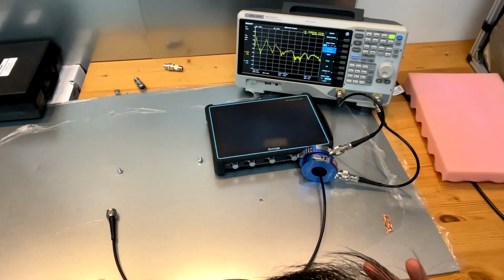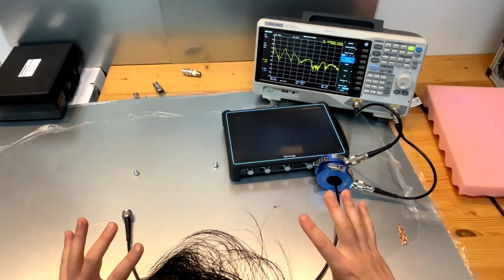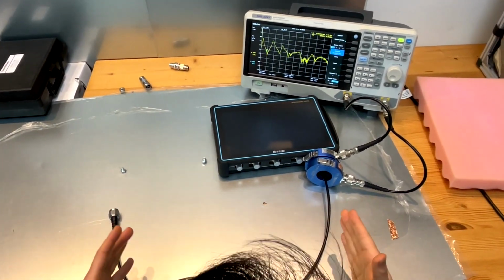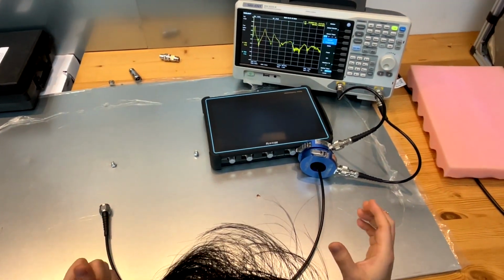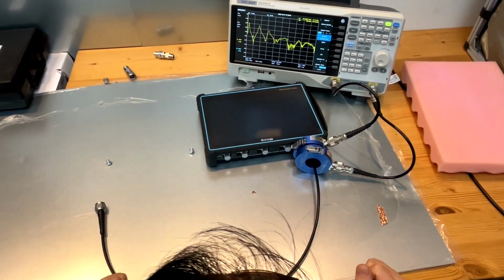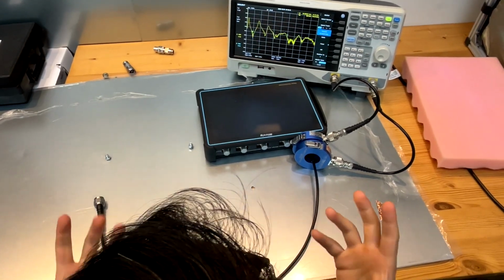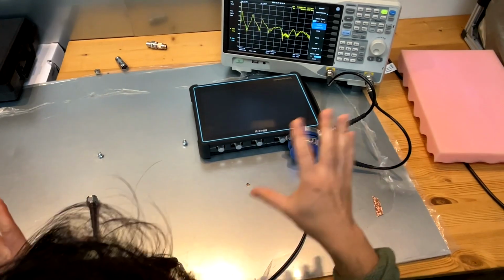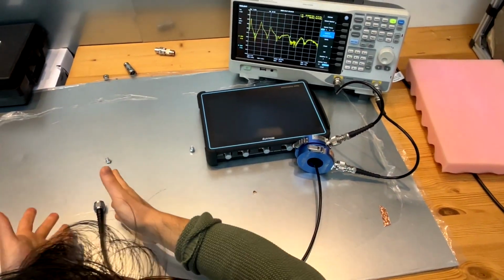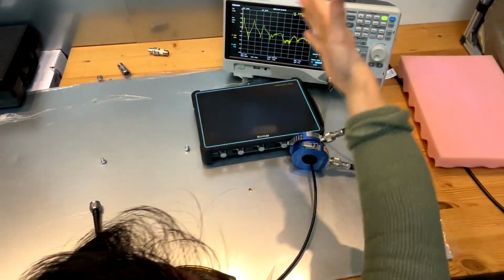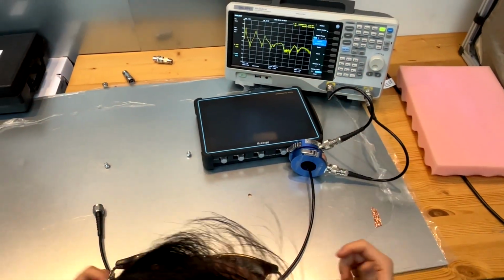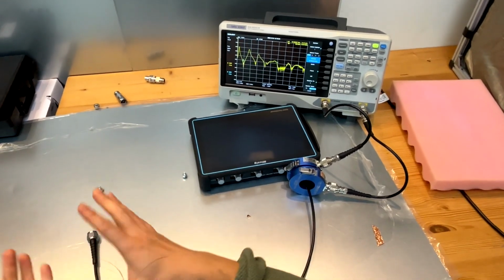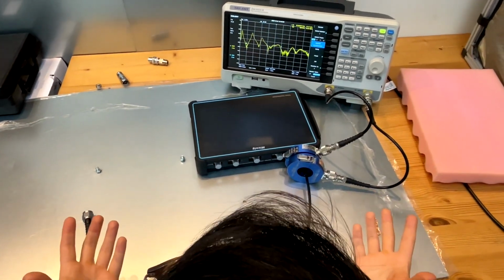Okay, we can do a lot to characterize and calculate this kind of resonance frequency, but perhaps the most important point from this demonstration is that a cable depends on how you connect it from the common mode point of view, right? It could be low impedance, high impedance, or low-high or high-low. Then your cable would behave differently. Sometimes it could be a half wavelength antenna, sometimes a quarter wavelength antenna.